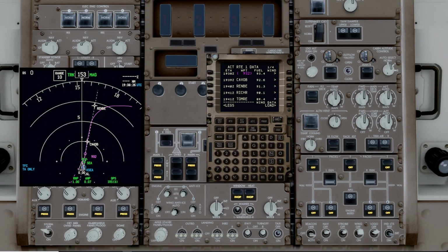And we left off with the CDU pre-flight. One thing we didn't do, and we can do, is load the winds that we got from our company from the data link. To do that, I went to the legs page, and then from the legs page, down here at 6 right is route data, and then we can either enter these manually or have them data linked in the form of an uplink to us.